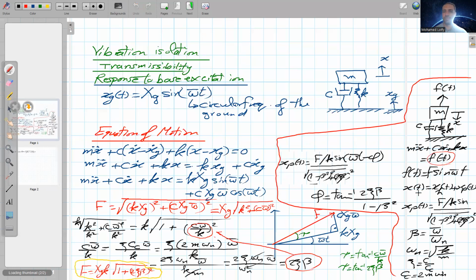This is the amplitude of the red force in this slide. And what angle? We want the projection of this resultant force on the vertical axis, because when you use the two components of this force, you also take the vertical projection, since you take sine omega bar t here. This is the vertical projection of this part, and here cosine omega bar t is normal to that one. We all know that this angle is also omega bar t. When you look at this part of the force, xg omega bar t cosine omega bar t, this is also the vertical projection of this part. So this is the resultant of these two forces, and taking the vertical projection of this force on the vertical axis is equivalent to taking the vertical projections of the components of these two forces.